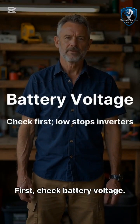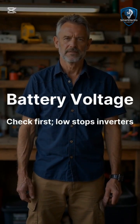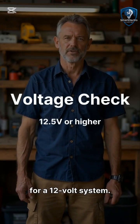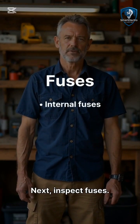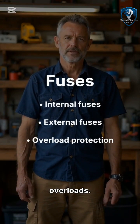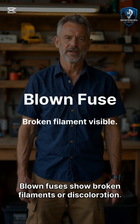First, check battery voltage. Low battery is the top reason inverters won't start. Ensure voltage is 12.5 volts or higher for a 12-volt system. If low, recharge or replace the battery. It lacks power. Next, inspect fuses. Inverters have internal and external fuses against overloads. Blown fuses show broken filaments or discoloration.